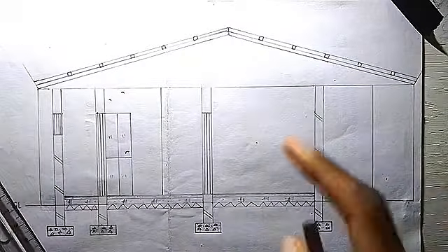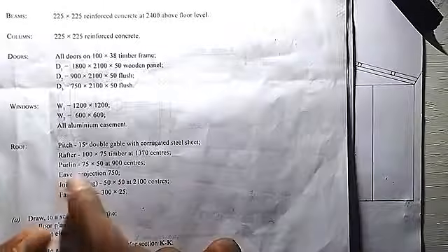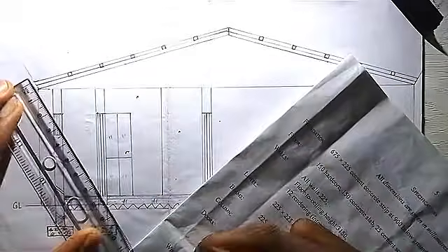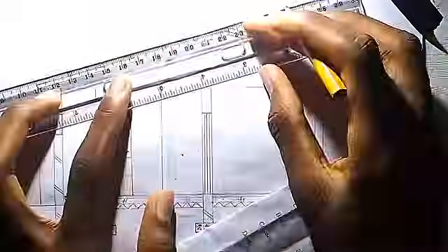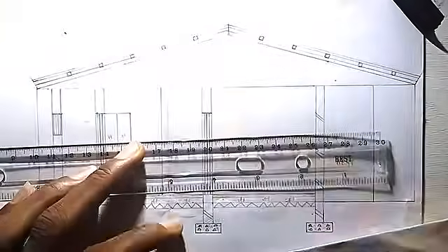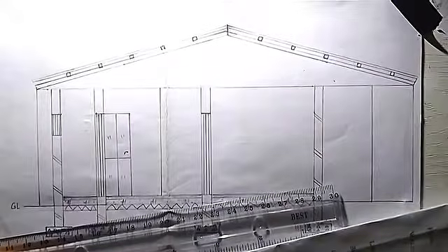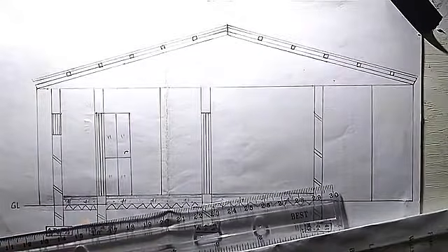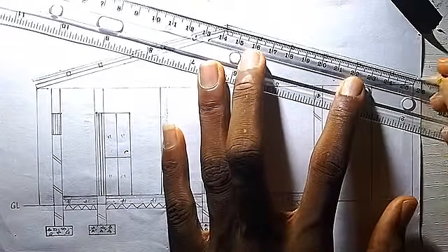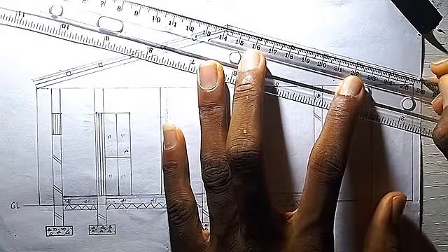Then after the purlin, we have the eaves projection. But before then, we'll just put our roofing sheet. The roofing sheet can be 0.1 cm. It's not always indicated, so just mark 0.1 here. So that's for our roofing sheets. Then the roofing sheets can extend downwards by 0.2 cm, which is here.